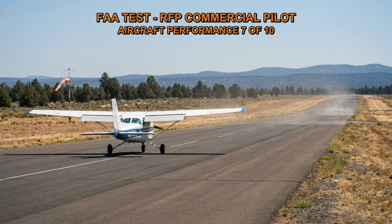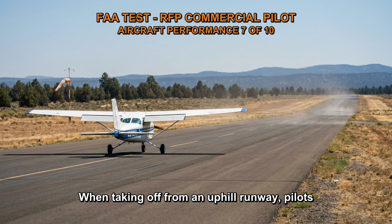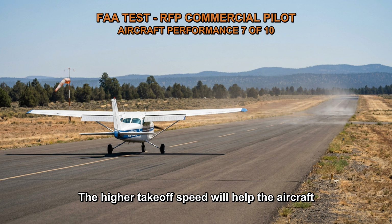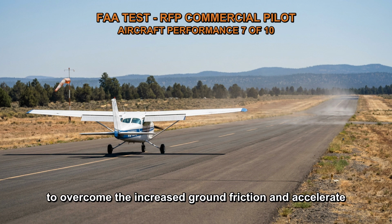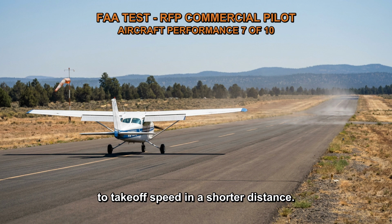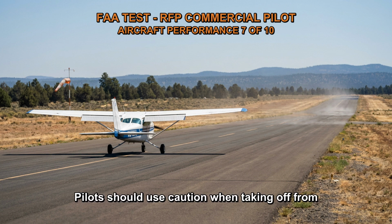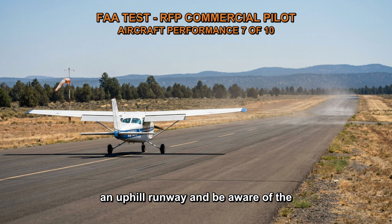Takeoff considerations. When taking off from an uphill runway, pilots should use a higher takeoff speed. The higher takeoff speed will help the aircraft to overcome the increased ground friction and accelerate to takeoff speed in a shorter distance. Be prepared for a longer takeoff run. The pilot should be prepared for a longer takeoff run in case the aircraft does not reach takeoff speed in the available runway length. Use caution. Pilots should use caution when taking off from an uphill runway and be aware of the increased takeoff distance requirements.